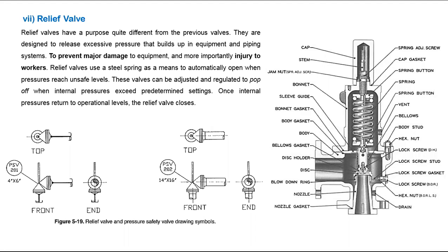Simply, for plastic pipe, if you are giving 6 bar, when you open the tap, because of the water hammering, the pipe will burst or the joint will leak. Everything will happen. Always it will happen. So you have to maintain a maximum of 4 bar pressure only in our plumbing system. If it exceeds 4 bar, you have to give pressure relief.